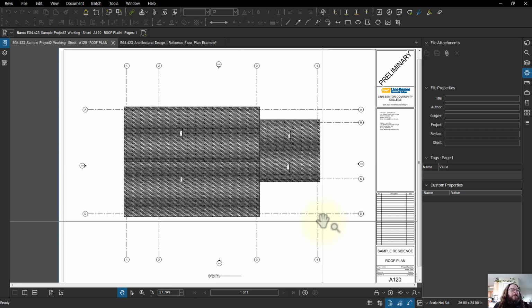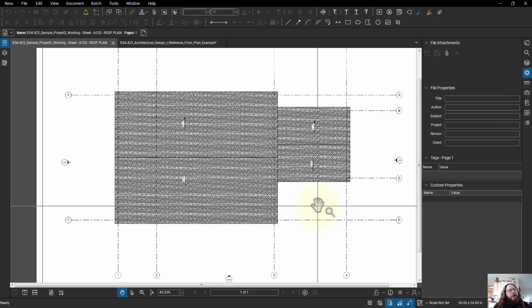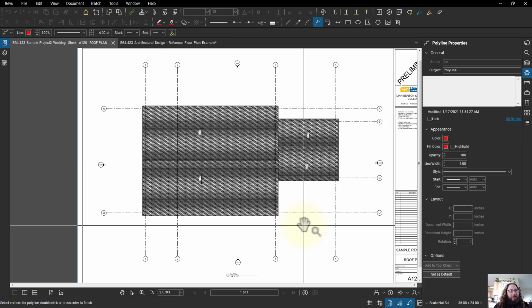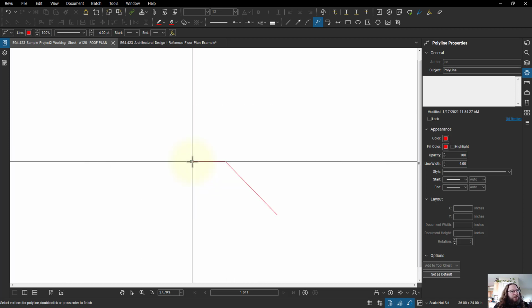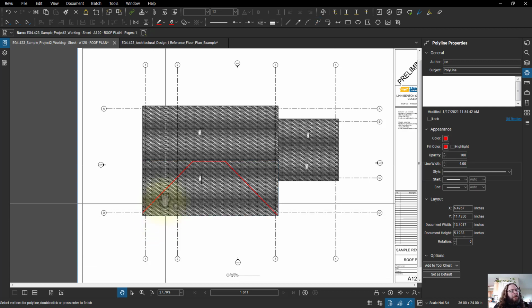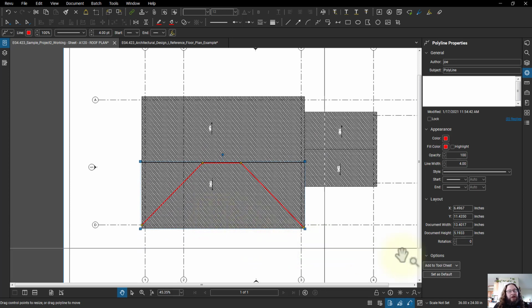But if you noticed in my roof plan, I changed the way that the roof is sloping. So if we were just to hit OK, it would give us a roof based on the outline, and as you can see, what it did is it went 45 degrees up this way to the ridge, and then back down to this side. Obviously it would be lined up with that corner, but that's okay for these purposes. You can see the difference between what it did and what we want.